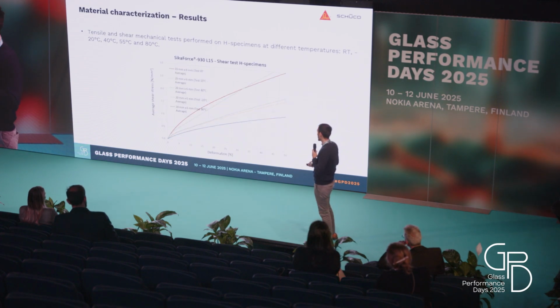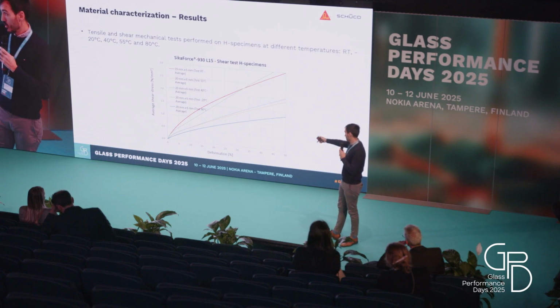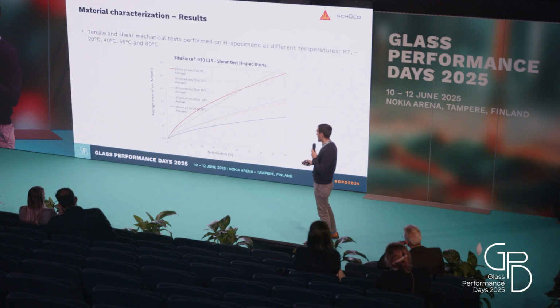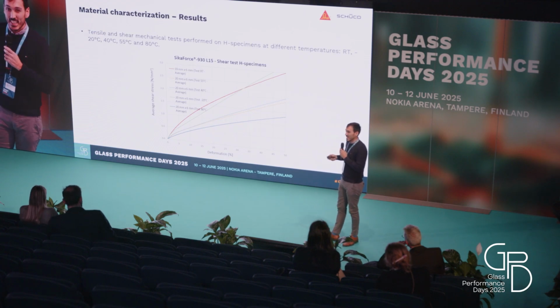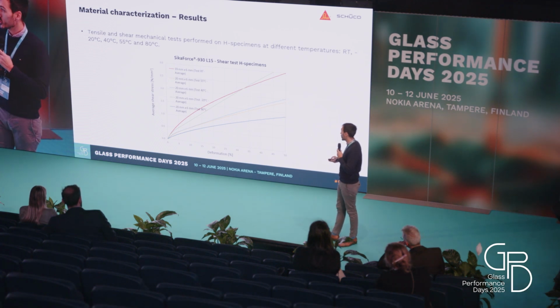But for us, it's really important that the material is quite stable over a long range of temperature. Then for the CR test, we see a similar behavior. We have the drop, the blue line is 80 degrees, logical with the temperature. And also a good point is that the low temperature is not making the adhesive heavily rigid. This is quite good because of the thermal dilatation and so on.